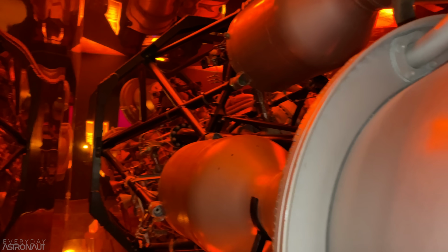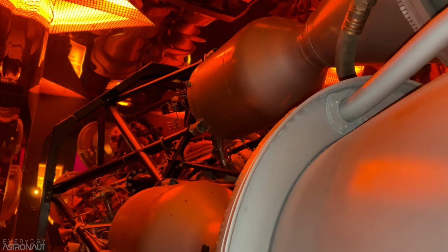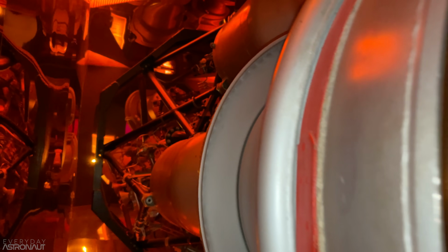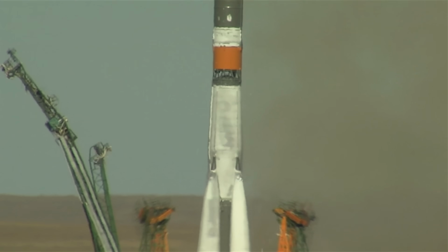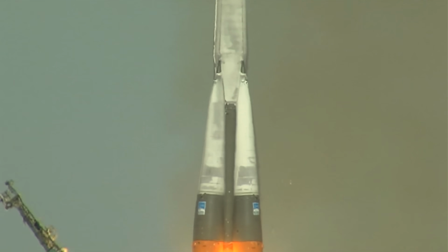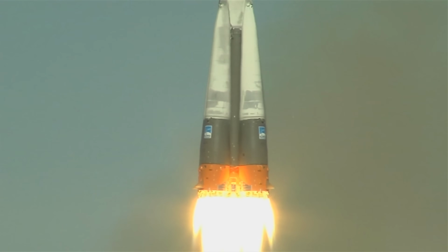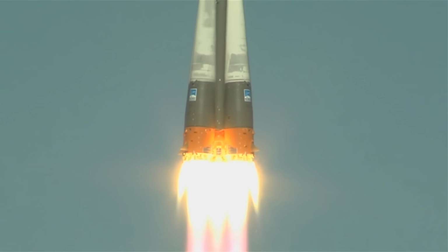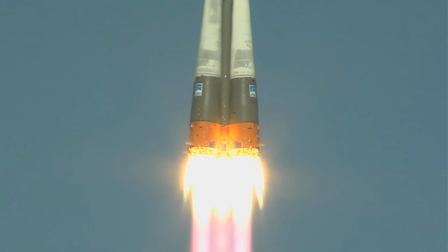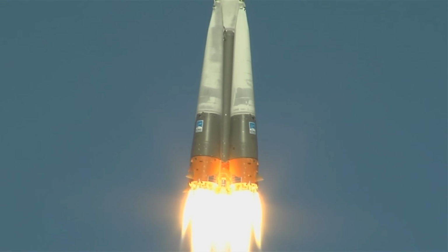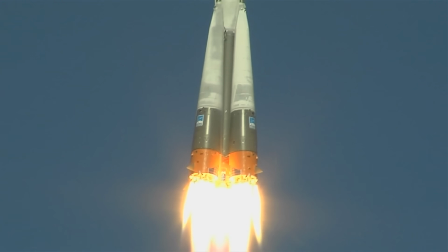It's a pretty clever idea, and it's still in use today on the Soyuz rocket on the RD-107A and the RD-108A. But that's a little less efficient to have another set of tanks for your gas generator fuel, and then you're also only getting the energy from a monoprop engine, instead of just tapping into the high energy rocket fuel that's already right there inside the rocket.